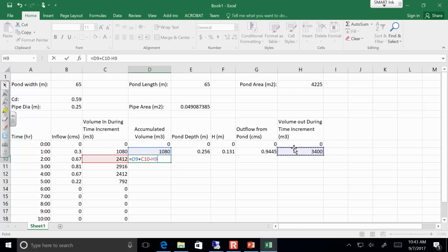the previous hour. Now this is one of the limitations of numerical integration, that here I'm doing it in hour by hour steps. It would be better if I had this data in 5-minute steps, because what we're essentially saying is that the outflow from the previous hour is what we're applying to conditions during this hour. But we're forced to do that. We have no other choice.